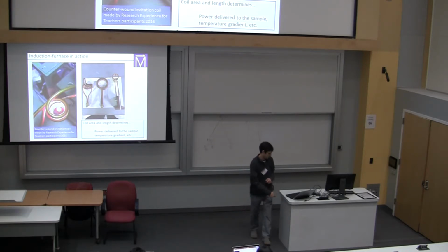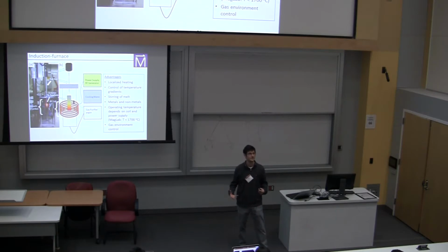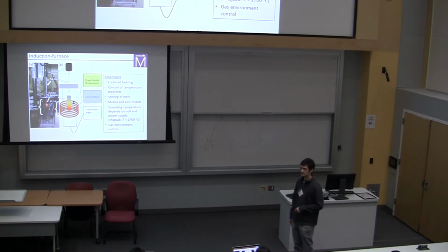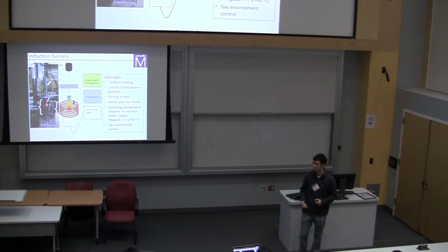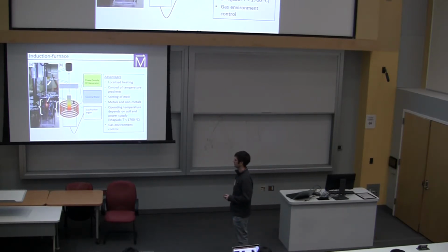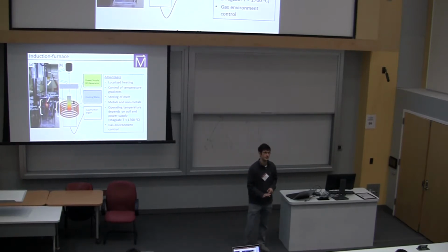Now, I want to remind you of something. I probably don't need to actually show you, but we have this quartz rod around the sample for our real growths. The trouble with the quartz rod and the pyrometer is that some of the intensity of light that comes out of the sample gets scattered in the quartz rod. So you're not making a truly quantitative measurement of the temperature when you try to measure it through the quartz. We estimate that the readout temperature is different from the actual temperature by about 10%. That does present some issues. Your actual knowledge of the temperature may be fairly limited.